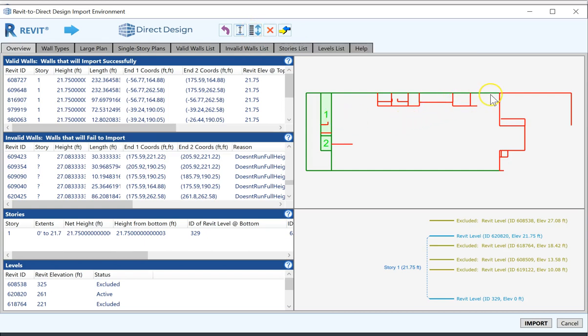And you can see some things have changed. Some of these walls have turned green, which is good. It means that we're getting closer to being compliant. We've got a problem though. It's identifying structural building sections here between some of these interior partition type walls. And we don't want that. Having some of these walls left in the model here can be okay, but only if they're in red, where they're going to get filtered out anyway. When they start to define sections in a way that we don't want, then they're causing trouble. So I'm going to select this one and just remove it.